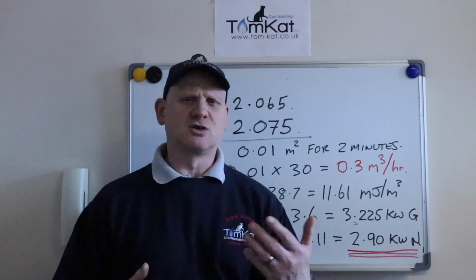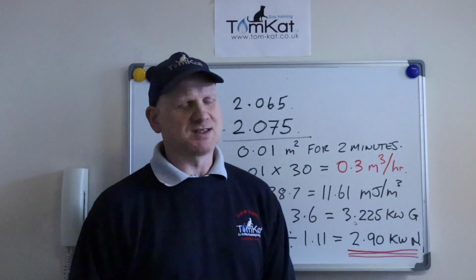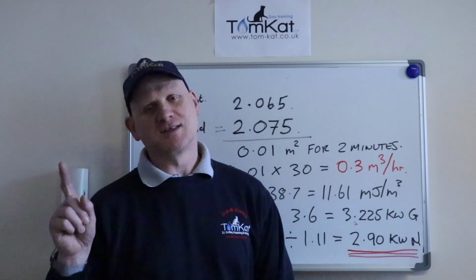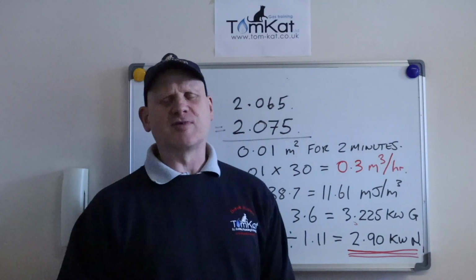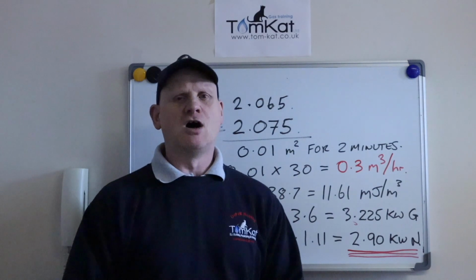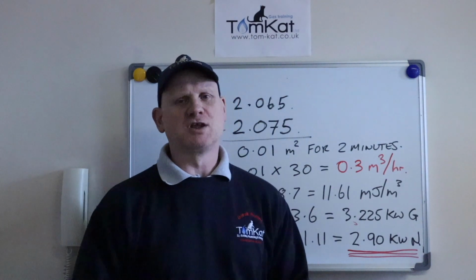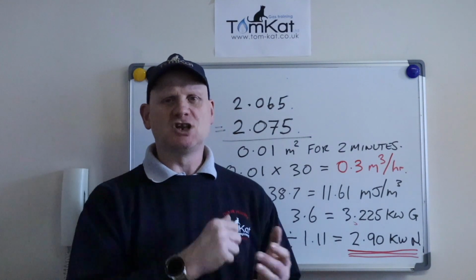You've also got to look at the flame picture. Okay, is that flame stable? Get it out in a minute. So it's not just the gas rate, because we have to look at other things, but the gas rate is a good indication of whether the appliance is burning correctly. Okay, now that's using a G4 meter.